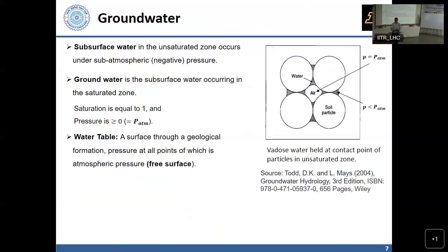Classification of aquifers. So we'll talk about confined aquifers, where, as the name implies, we are expecting that water can be confined and can stay under pressure. So we need confining layers both on top and on the bottom, sometimes called pressure aquifers. So both on the roof and the floor of the aquifer, we have to have either impervious formations or at the very least semi-pervious formations for it to behave in a confined fashion.